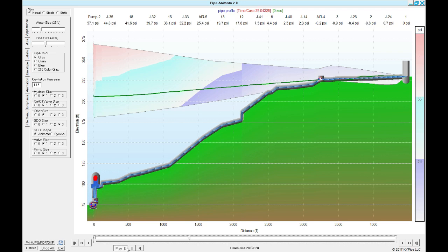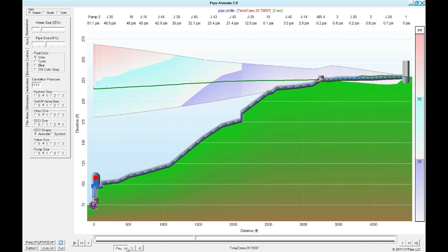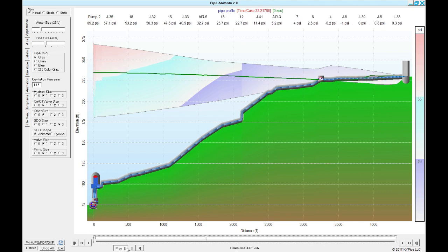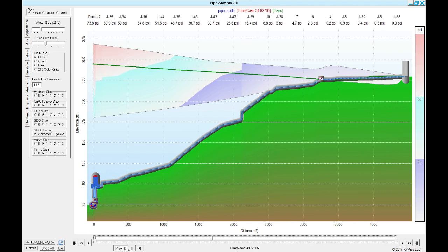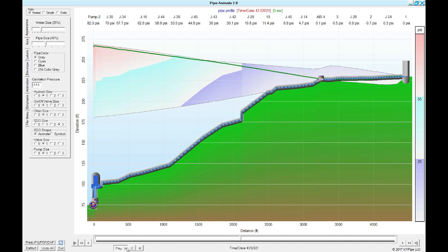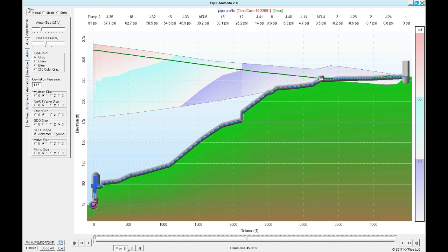If you haven't guessed by now, this is a force main system example, not a potable water system. So the negative pressures that we are experiencing are acceptable for this application. In conclusion, a surge analysis is best to be performed to ensure proper mitigation efforts are taken under all operating scenarios.